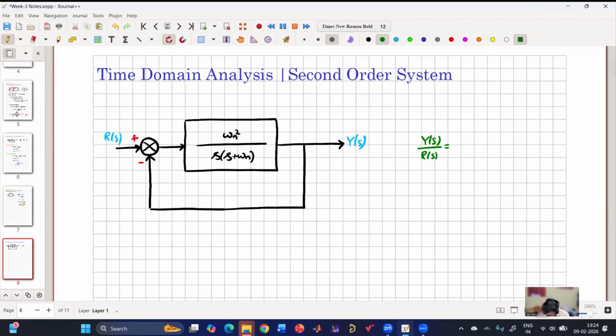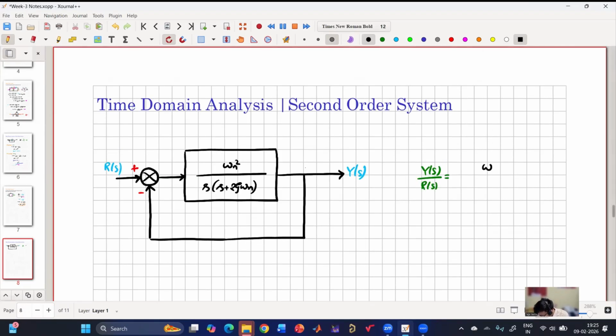Sorry, this is not the generic one. I made a mistake. It will be s into s plus 2 zeta omega n. Okay, can anyone tell me what will be the final transfer function for this unity feedback system? Omega n square by s into s plus...